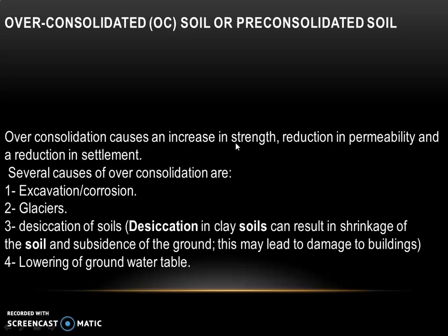Over-consolidation causes an increase in strength, reduction in permeability, and a reduction in settlement. There are several causes of over-consolidation. They are excavation or erosion, glaciers, desiccation of soils, that is shrinkage of soil, and lowering of groundwater table.